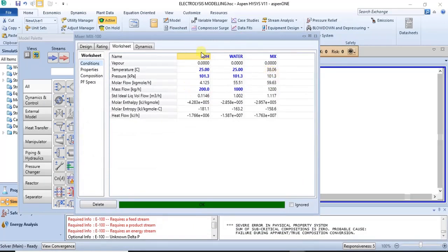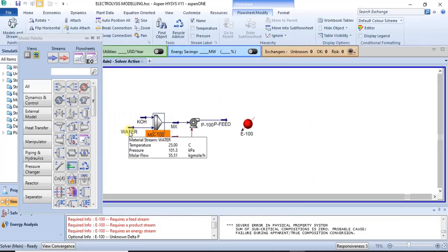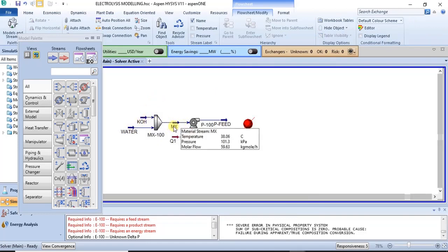So I guess when you want to specify your alkaline medium, you can still add some water to this alkaline feed, in as much as water is actually the feed to the process. You can still add a little water to the KOH feed just to maintain the temperature of the outlet, right? And also remember what I said earlier, the weight percent of the KOH has a specific range. I think it's from 25% to 35%, right?